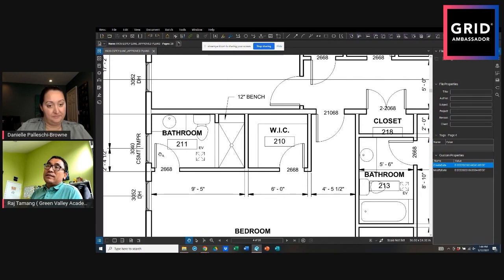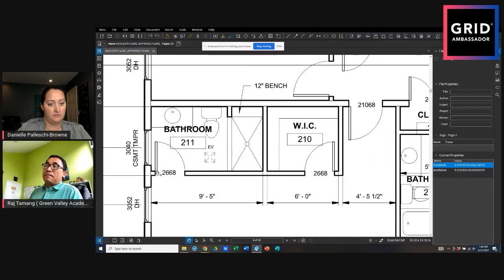So these locations, even though I don't have to, because of how you have installed the door, left hand in swing, the door may hit the glass. So that glass has to be tempered. That makes a lot of sense.